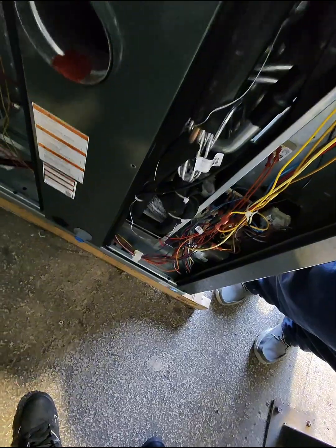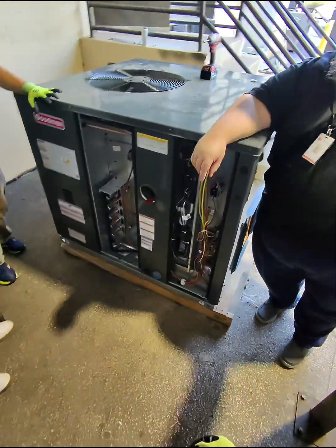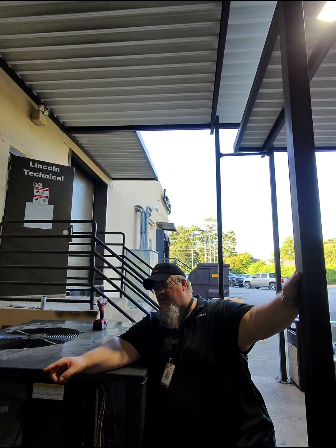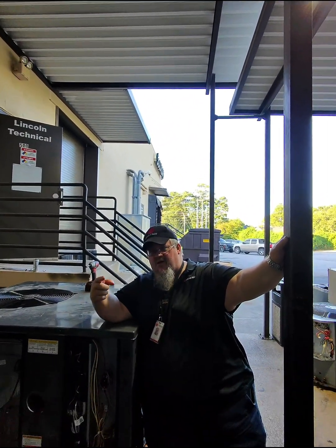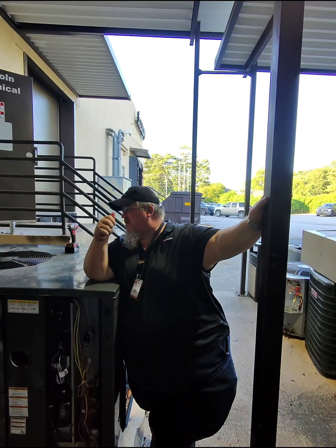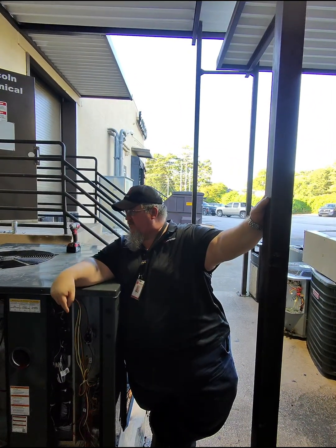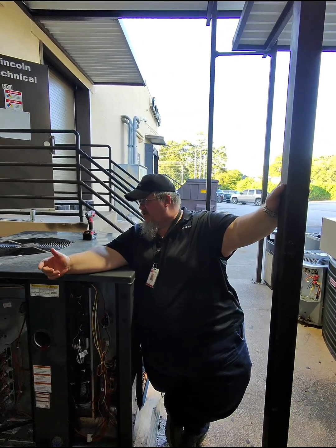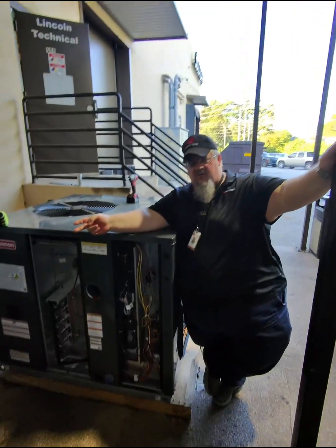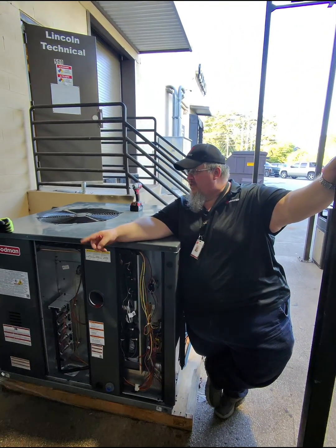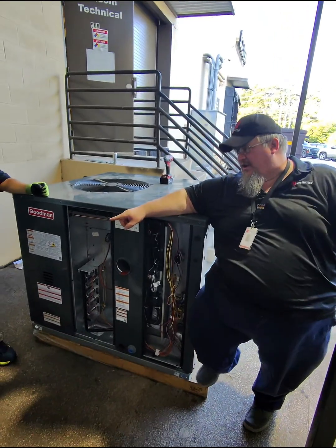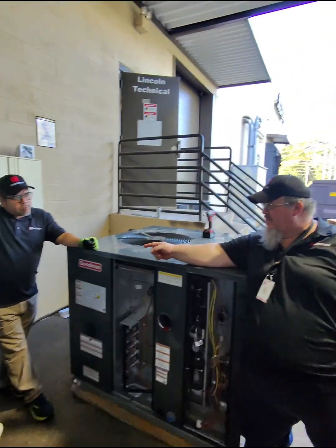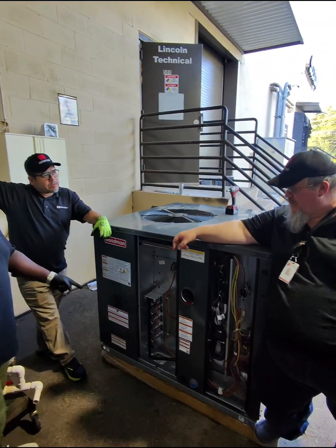On your igniters, and especially your spark igniter, you can't use just any wire. It has to be rated for that voltage. It's like 10,000 volts. It's not just any wire. You have to make sure you have the right spark igniter wire. But you're correct, it's a spark igniter. What happens? Your igniter comes on, right? What comes on then? The gas valve. Where's the gas valve?